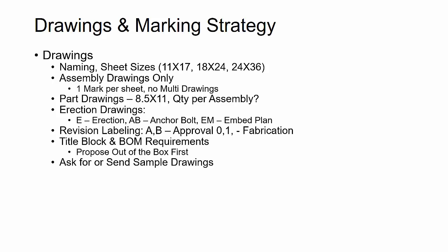Find out what the revision labeling is, title block and bill of material requirements, and even ask them to send sample drawings. Again, stair drawings can sometimes take a lot of manual cleanup time depending on the standards of the fabricator. If you just do the dimensions and stairs all by yourself without any fabricator input or looking at their standards, you may end up finding that you're going to have to do some redetailing.